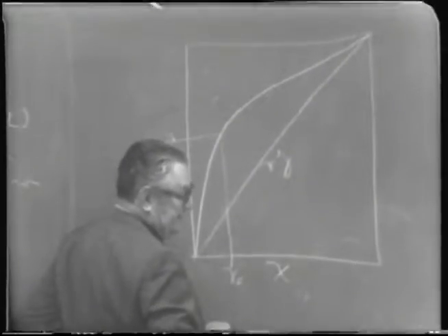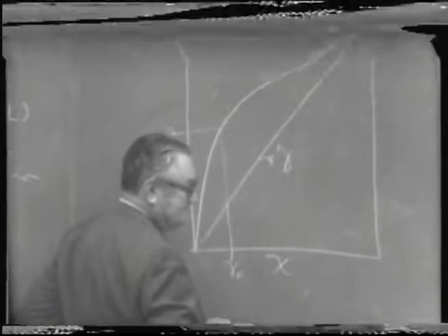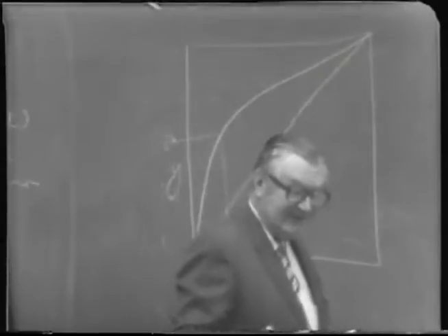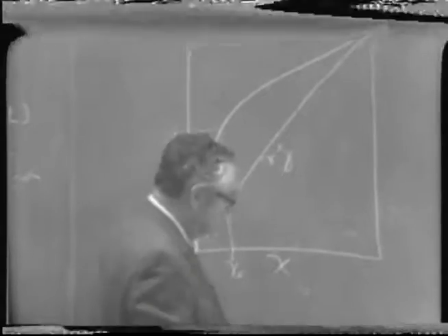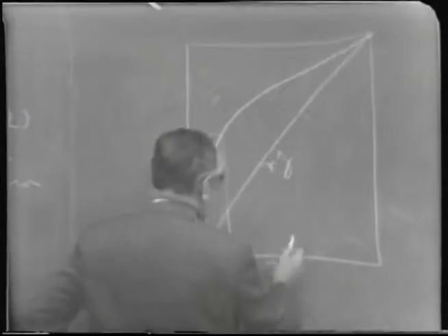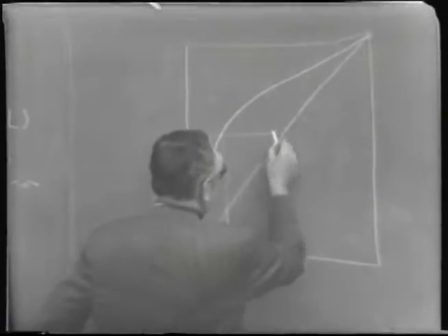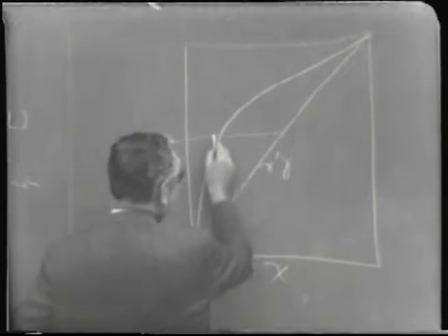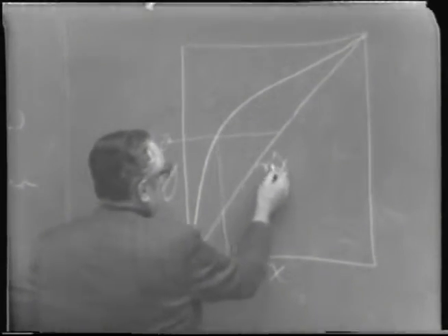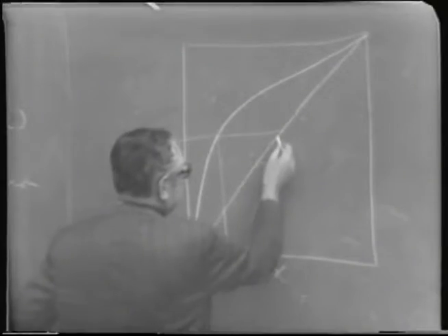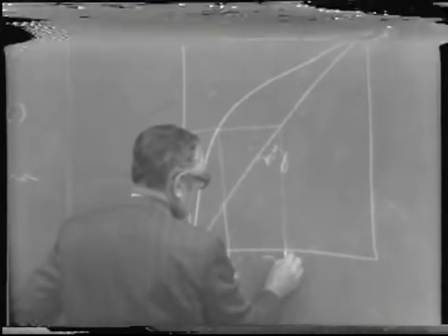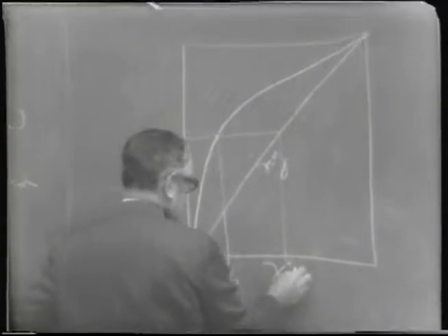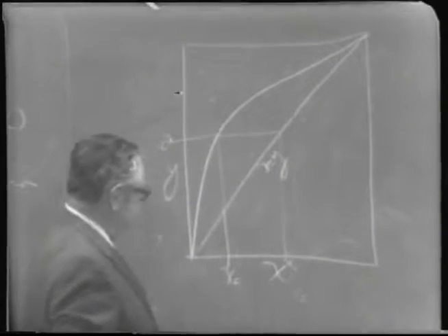Now, if we take that vapor and condense it, well, then we're back to a liquid phase again. And the composition of the liquid phase that we'd have available for the next vaporization would be given by projecting this over to the diagonal where x is equal to y. So now we're back here to x1. We'd call that x1.